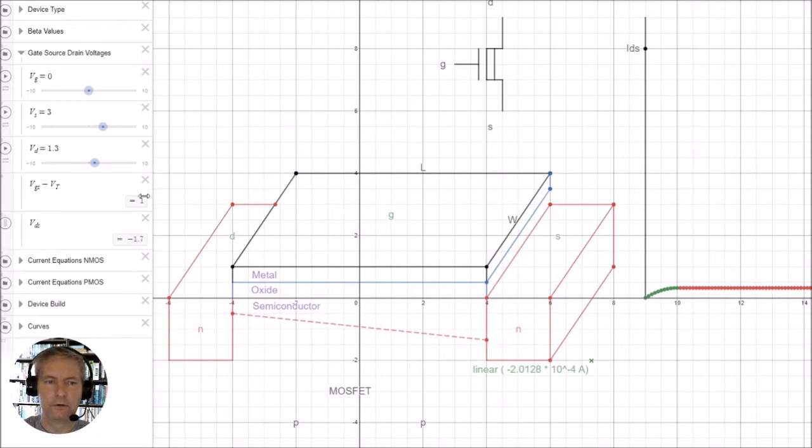And you can see here that we've got that partially modelled in the diagram here, because the current is actually now going to be a negative value, and the drain source voltage is going to be negative as well, because the drain and the source have been switched round. But we're not going to use the device like that. We're going to keep these represented as they actually are. That is, the drain voltage is going to be greater than the source voltage, just to avoid any confusion. So we will be running it in effect in this region here.